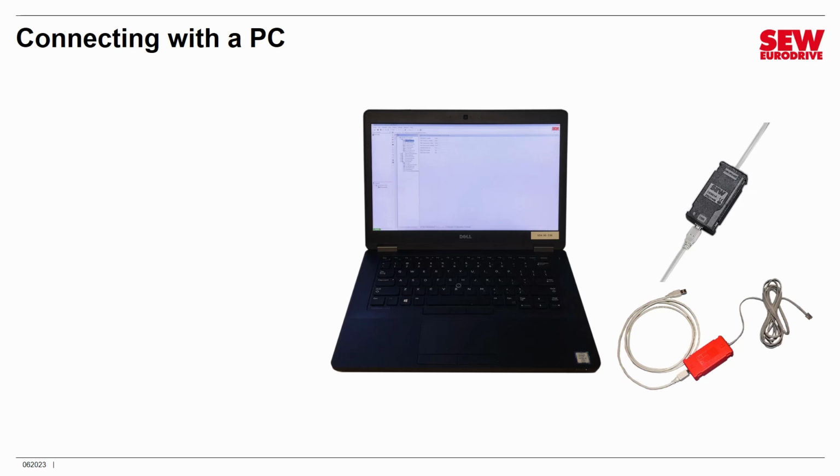You do need to have the appropriate cable on it, and you'll need the one that looks sort of like what you would see on an old-fashioned landline phone's handset. It's sort of a small version of the RJ45 plug. You will need to have that particular cable to connect to the diagnostic port on the MOVIMOT.